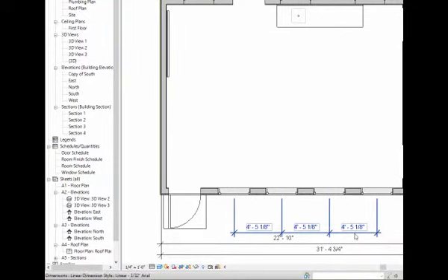Now, a cool thing about strings of dimensions is this. Strings of dimensions have this notion that when you choose them, there's a little equality relationship in there, and you can see right now we're not enforcing it. When Hong put this together, he actually put them together equal. So let me move one of those windows over a little bit, just to make them unequal.